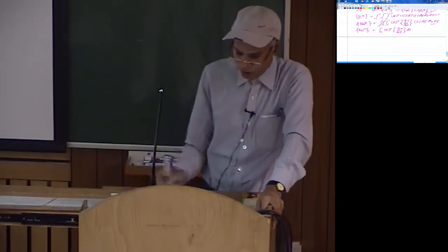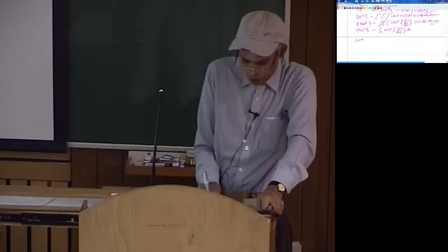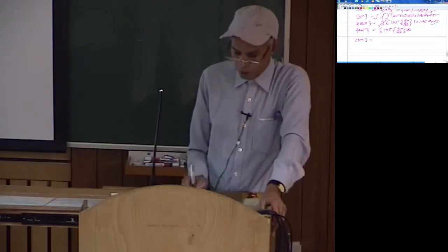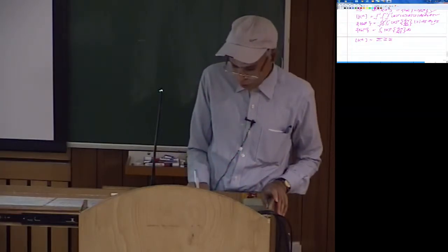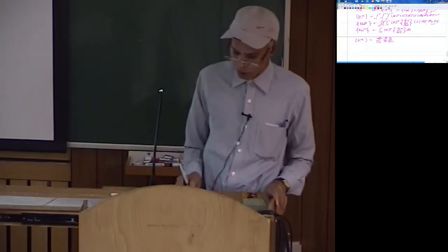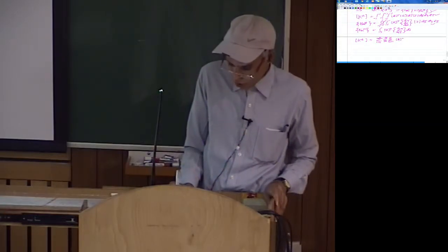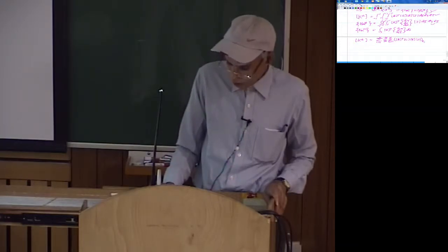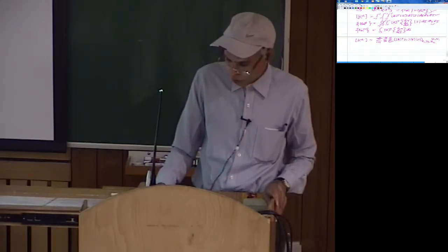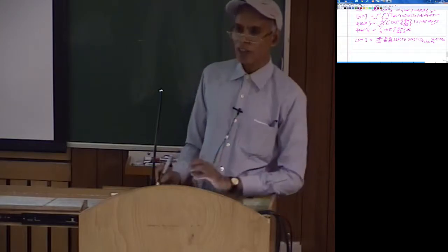So for the integration, if you look at the KE, like we did for the 2D problems, this is written as summation over, say, i equal to 1 to n, j equal to 1 to n, and k equal to, let us say, 1 to n, where n is the number of Gauss points, and then B transpose into C into B into determinant of J. This whole thing is evaluated at, say, xi i, eta j and zeta k into wi, wj, wk. So these integrals are again evaluated numerically.